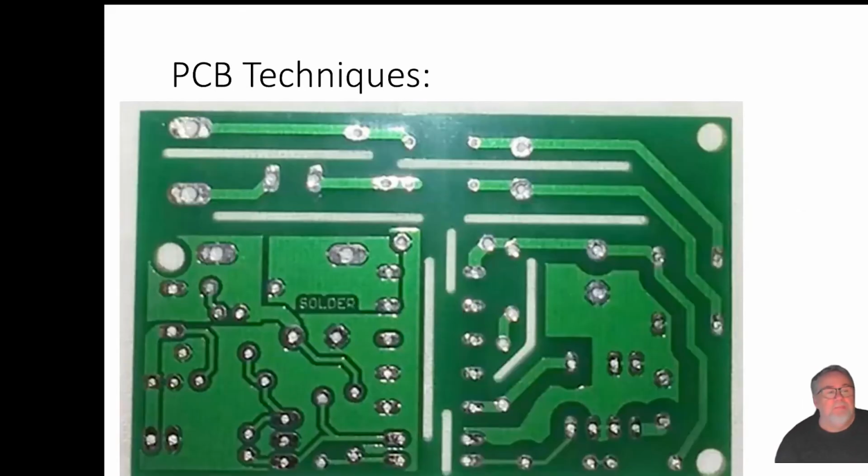And printed circuit boards. This is a printed circuit board for a switched mode power supply. If you look at the top, without ever seeing the circuit, the mains comes in at the top, and you see these slots, you can see the holes. And through the holes, you can see the background. And you can see that apart from the round holes, there are slots, long slots, that have been routed in this board.